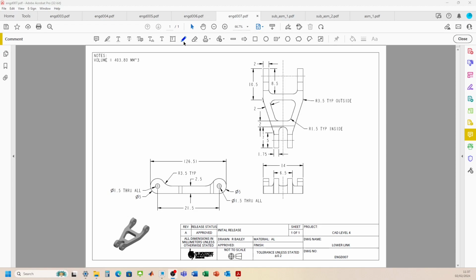Okay guys, before we go in and start modeling this, let's review the engineering drawing. So for this one, it's a nice component. Again, we've got a nice line of symmetry, so that's going to help us out. I think for this one, I'm going to approach it where we draw the side profile. So we're going to ignore the rounds to start with. We'll put those in at a later date.